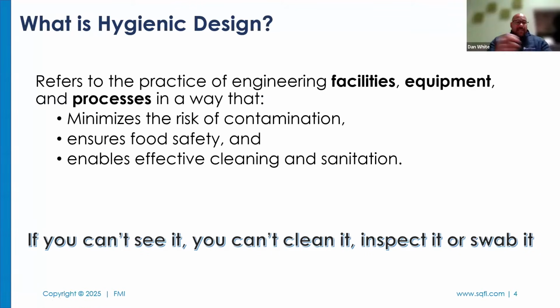All right, so what's hygienic design? For some people, it's a foreign concept. For a lot of the larger manufacturers, you have a pretty approved process of actually onboarding a new piece of equipment. But hygienic design refers to the practice of engineering facilities, equipment, and processes in a way that minimizes the risk of contamination, ensures food safety, and enables the effective cleaning and sanitation of that piece of equipment or area in your facility. Basic principle, if you can't see it, you can't clean it, inspect it, or swab it.